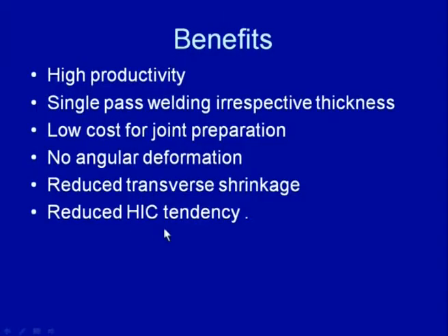Further, this reduces the transverse shrinkage also, and as I have just described, because of the low cooling rate, reduced tendency of martensitic transformation and increased tendency of escaping of the gases present in the weld zone, the hydrogen induced cracking tendency in electroslag welding is reduced significantly.